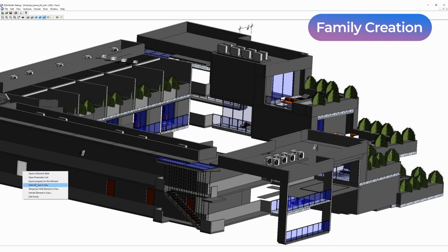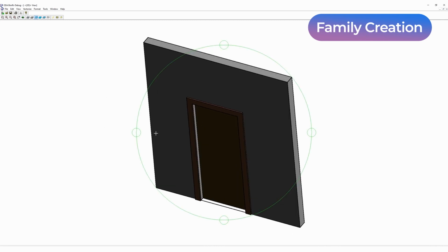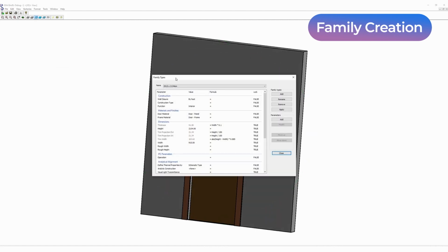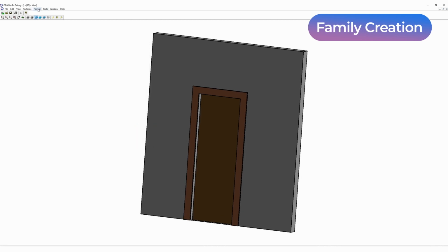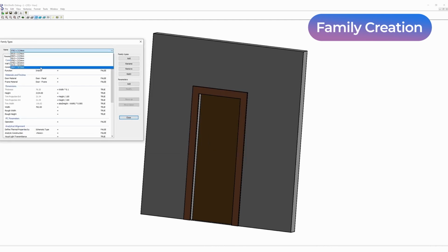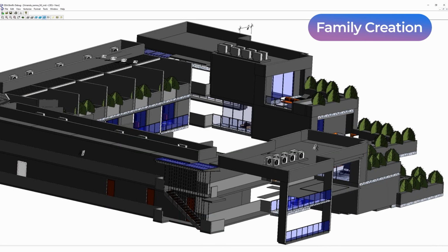Find elements which must be updated. For each element, we need to modify its parameters and run the constraint solver to solve the sketch for a new state. If it is solved, the element geometry must be rebuilt for the new sketch. And finally, create a graph of operations between elements and repeat them in the correct order. If all steps are done, we will get geometry for the new family type. This process works in family when you change family type, and it is also used for activation of family symbols. In this case, we try to rebuild geometry in a restored family database and collect the result to the symbol.